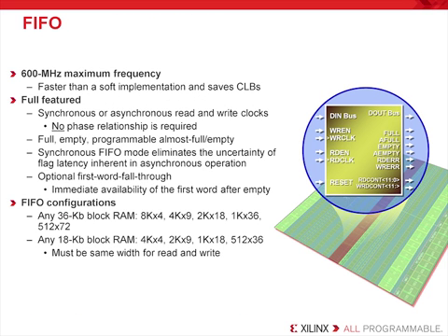Virtex 6 includes dedicated logic to convert each block RAM into a FIFO. This is of course going to have better performance than a soft-core implementation of a FIFO, and this will also save CLB resources since this logic is dedicated in the silicon. It is a full-featured FIFO that supports synchronous and asynchronous read and write clocks, so no phase relationship between the clocks is required. It has full, empty, and programmable almost empty and almost full flags. The synchronous FIFO mode eliminates the uncertainty of flag latency inherent with asynchronous operation.